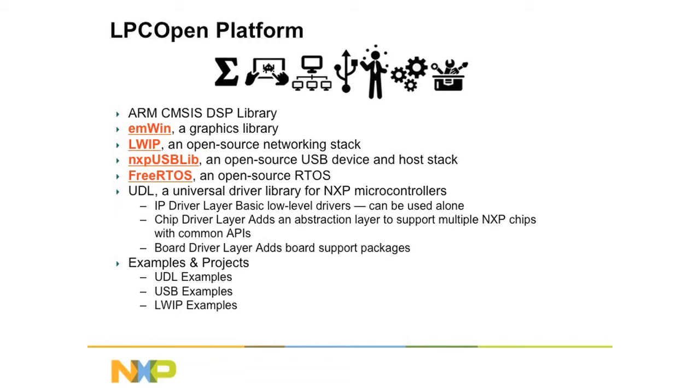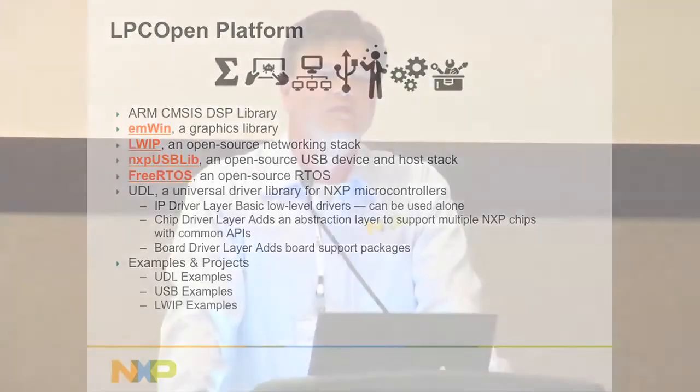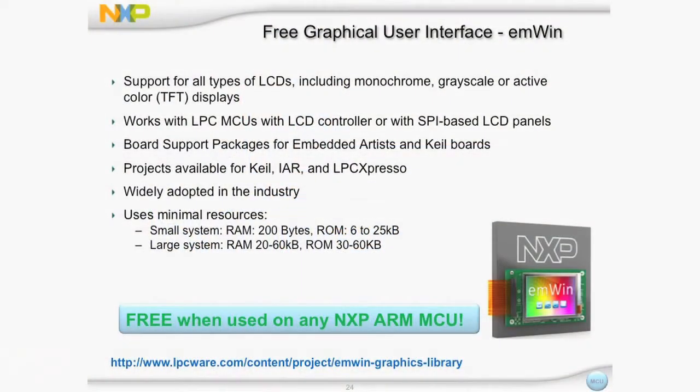And all of this is tied together into one big package that you can download for any of the major IDEs. For instance, if you want to use LPCXpresso, you download the Xpresso version of the LPCOpen Platform, and you get all of this code together with sample applications, so you can either start modifying those to suit your needs, or if you just want to experiment with them and see what they can do, you can just use them as is.